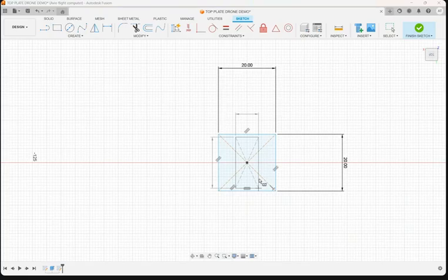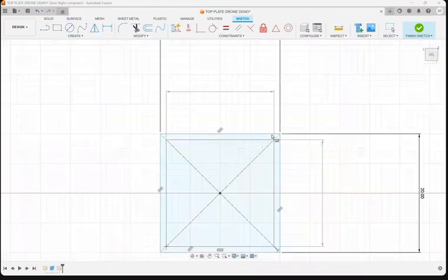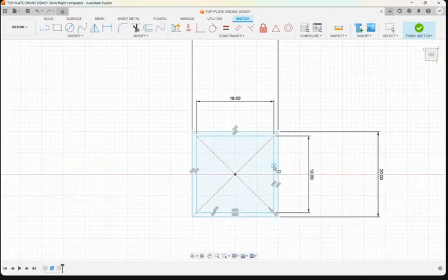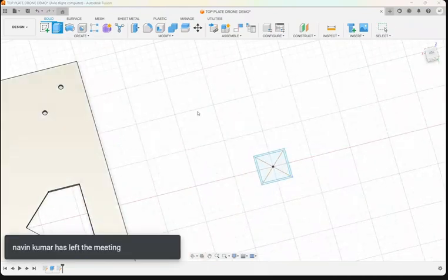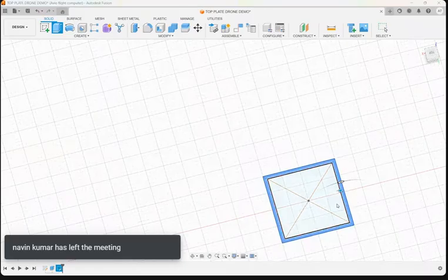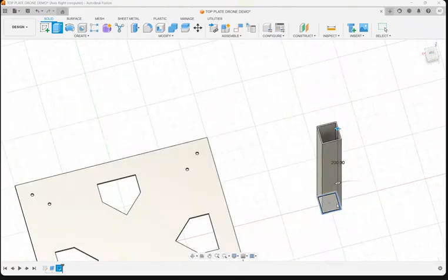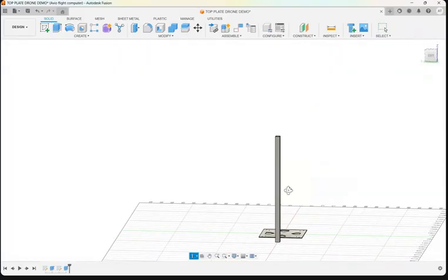And for making it hollow, we are giving this area. I have left an area of 2 mm cross 2 mm here, and made it hollow. Okay, I'll finish the sketch. If I choose extrude again and choose this area, suppose let's make it 20 centimeter, so that means 200 mm. Let's make it 500, a 50 centimeter rod.